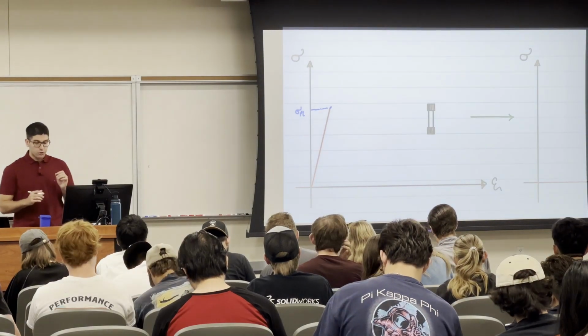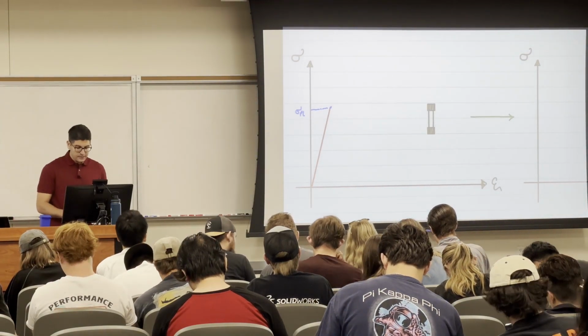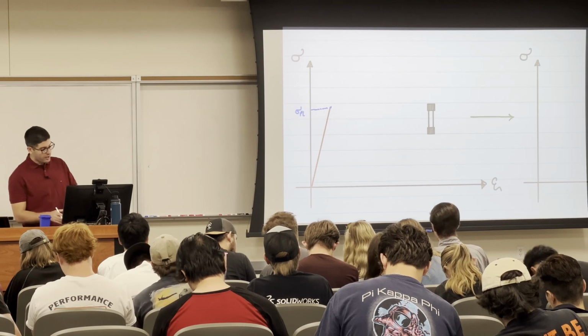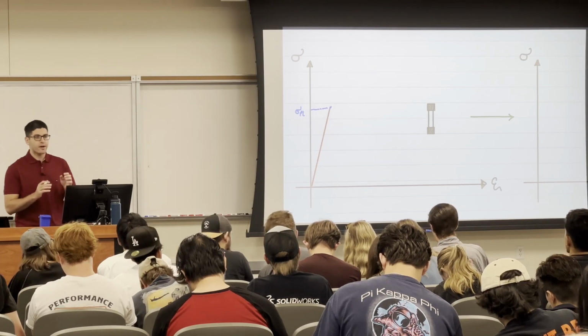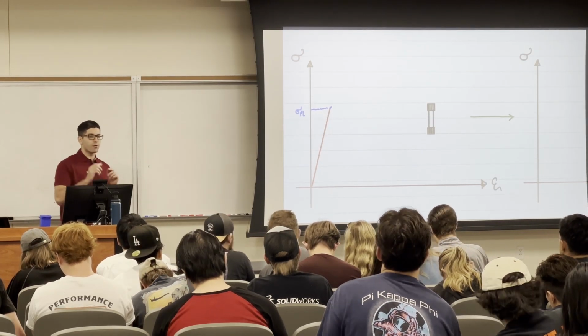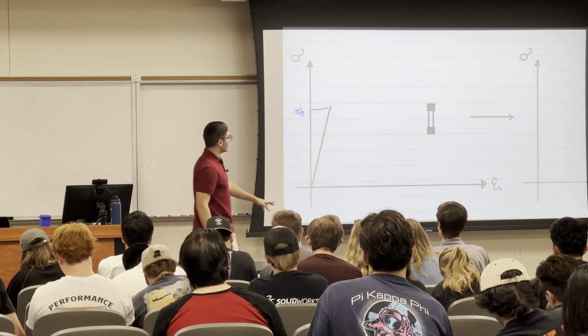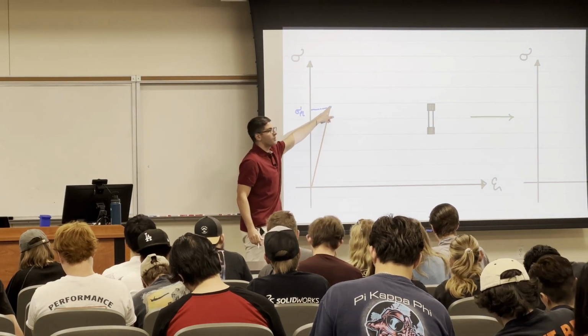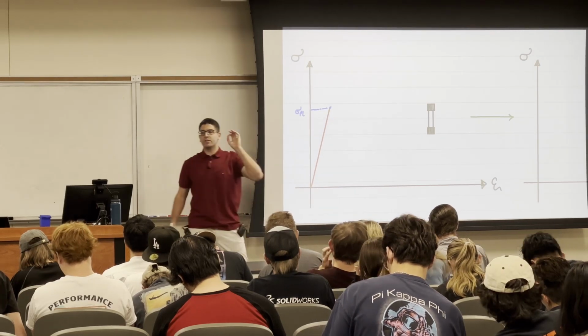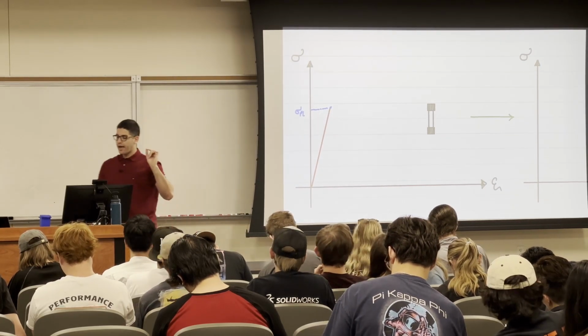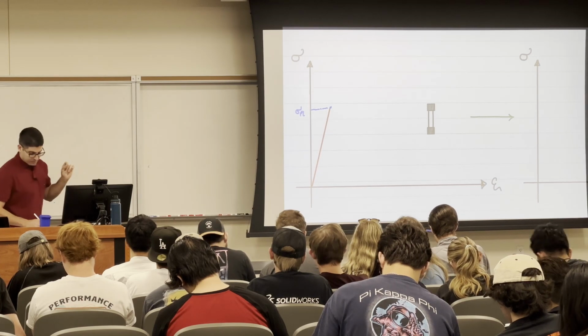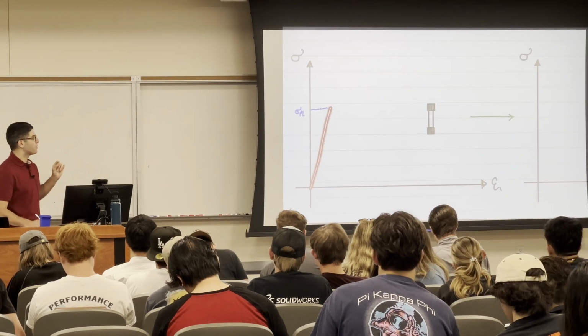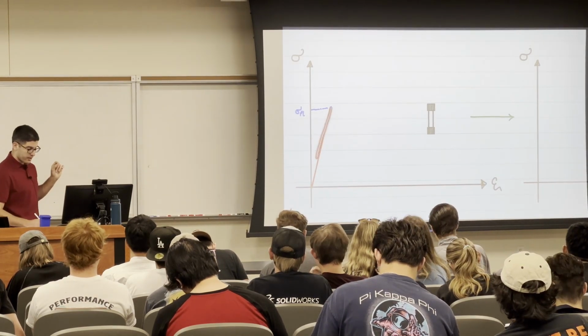And proportional limit is the last point in a line where the curve is going to behave in a linear elastic way. In other words, if I loaded this member until here and I unloaded, it's going to go back to 0.